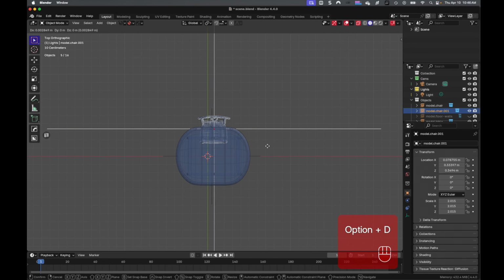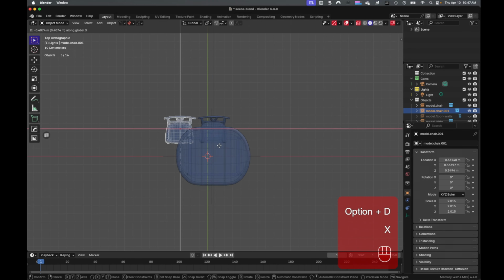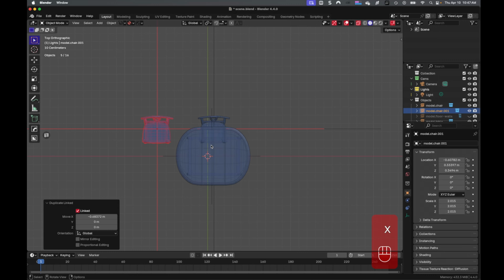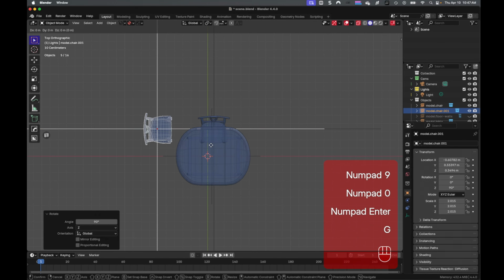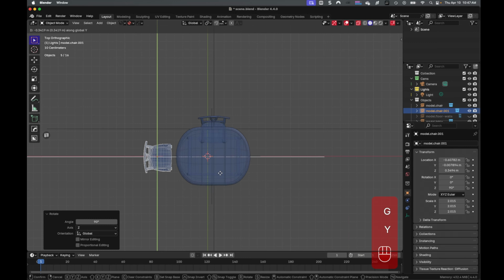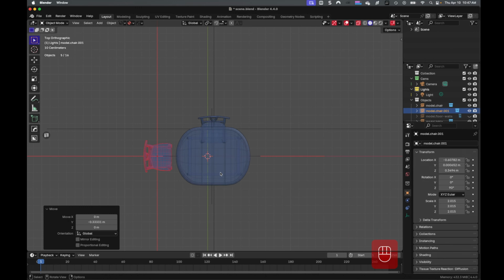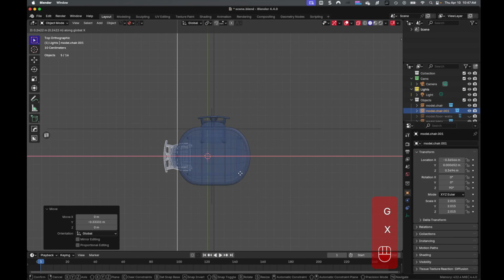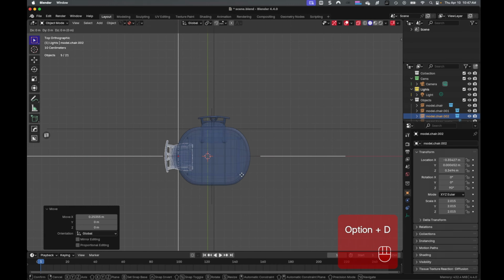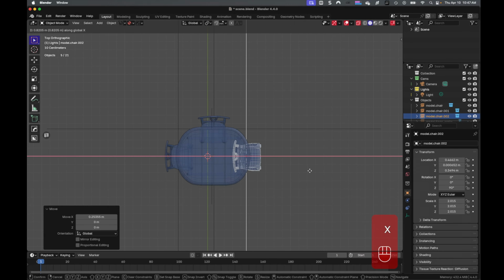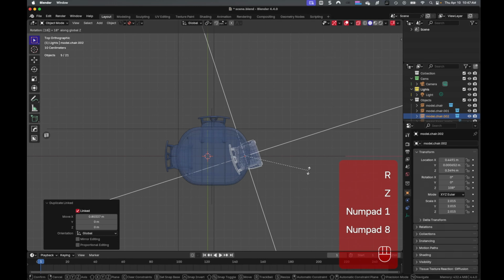Okay. So now I'm making a duplicate of the chair. I'm not making an alias. I'm actually making a copy of the chair. So in terms of Blender, this is a new model, but it is still linked to the original. So if I change that original file, it will inherit the changes in every copy that I have in this file because they're linked, if that makes sense.